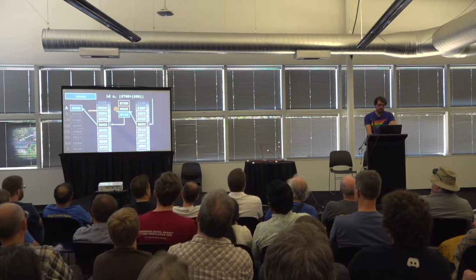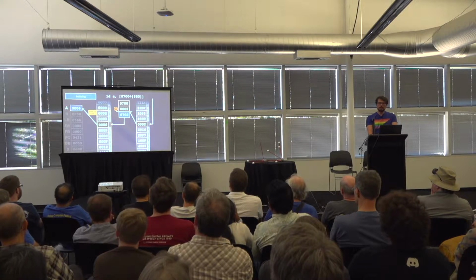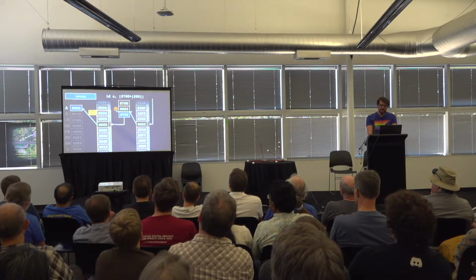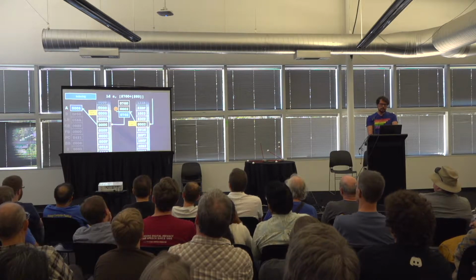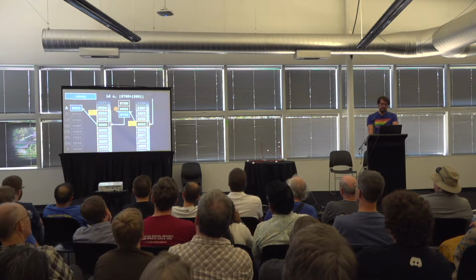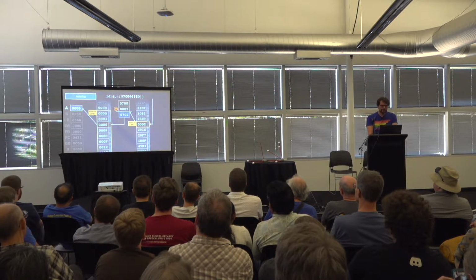There's a table in memory at 700. In the example, it contains multiples of 3, and an index into the table is stored in memory at 080, which in this example is 2. So we read the entry at index 2 of the table, which is 6.